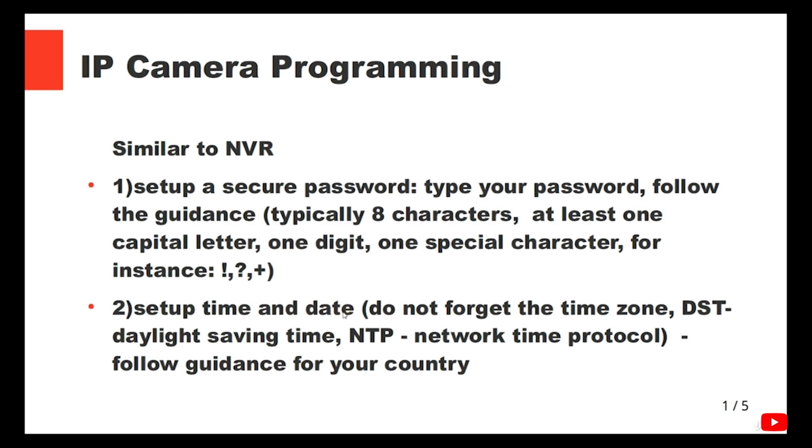Again, with IP cameras, it's extremely important to set up proper date and time, and do not forget the time zone, and then daylight savings time and network time protocol. Again, follow guidance for your country. Why is it important?